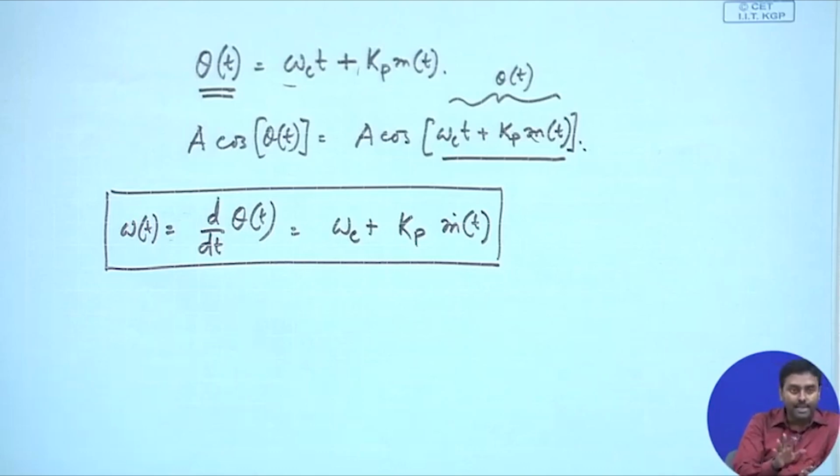So, what I can say, if I do a phase modulation, that is nothing but also a frequency modulation, but in the phase modulation I modify the phase with respect to m t, whereas if I have a frequency modulator, a similar phase modulation I can create if first I differentiate my signal and then do an FM. So, correspondingly what will be created, that should be my PM, right. So, phase modulation is nothing but I first do a frequency modulation, but when I do frequency modulation, I also remember that if I do the frequency modulation with respect to the differentiation of that particular signal, then automatically that depicts the phase modulation, right. So, this is what we are trying to do.